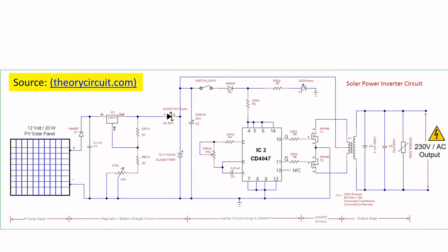Here we are making it work as an astable multivibrator. The IC will be working like an astable multivibrator, automatically switching between the two states continuously without any external trigger pulse. Another name for the astable multivibrator is a free running oscillator. But with the other multivibrators, monostable and bistable, in monostable you have one stable state and one quasi-stable state. In the bistable you have two stable states, but you need an external triggering pulse. For astable you need not have any external triggering.